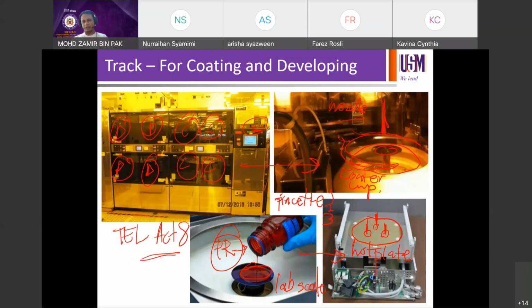Okay, so the moment the heating is completed, hot plate or cool plate, it's the same principle, just that one is hot and one is cool. The moment the heating is completed, the 3 pins come up again. The wafer has finished heating, it rises back up, so the wafer is floating in air on the 3 pins. Then the module opens, the pin set goes in, takes the wafer, goes out again, the 3 pins go down, the module closes, then the next pin set delivers. So that's how it works, pretty much, right? Okay, can you appreciate it?